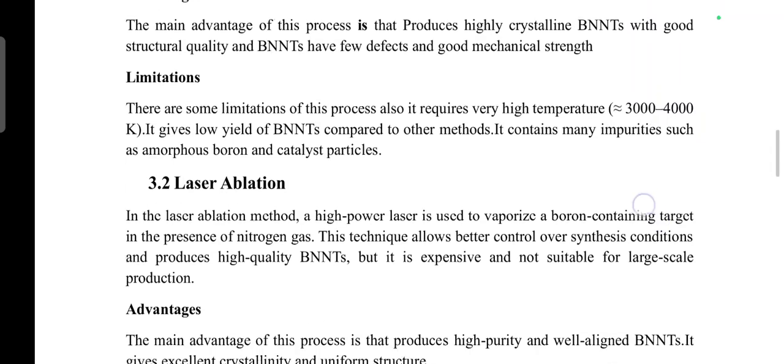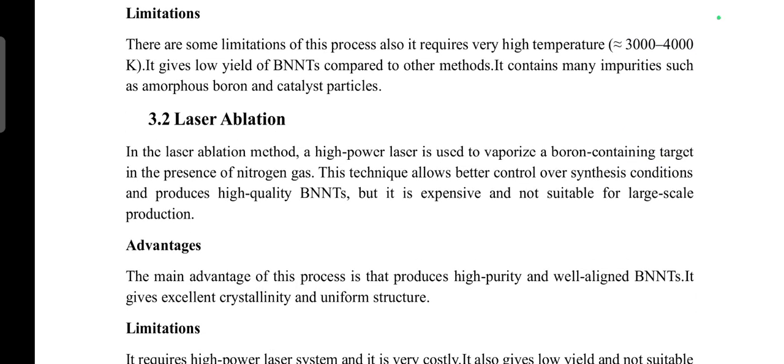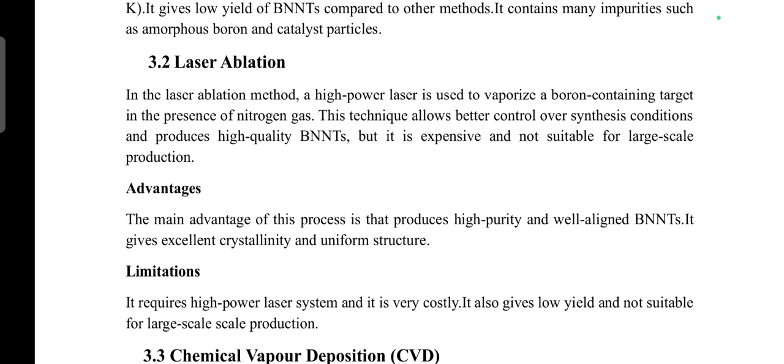Next, we will discuss the second method, the laser ablation method. What is the laser ablation method? In the laser ablation method, a high power laser is used to vaporize a boron containing target in the presence of nitrogen gas. We can say that there will be a boron containing target, which we will break down with the help of a high power laser beam in the presence of nitrogen gas.